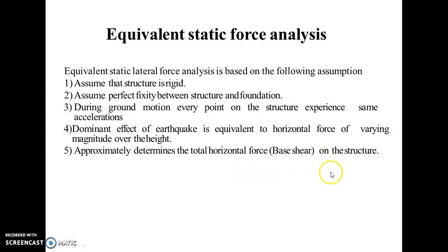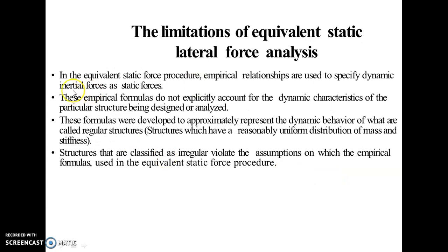There are some limitations also that we will discuss. The limitations are: in the equivalent static force procedure, empirical relationships are used to specify the dynamic inertial force as static forces. These empirical formulas do not explicitly account for the dynamic characteristics of the particular structure being designed or analyzed.